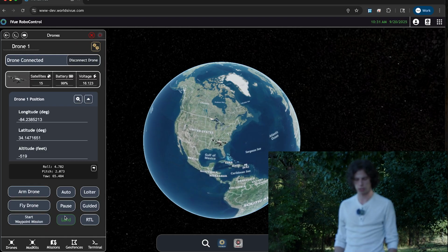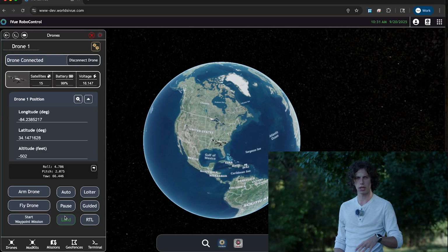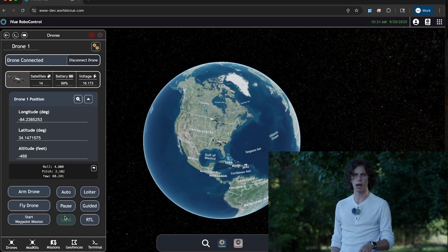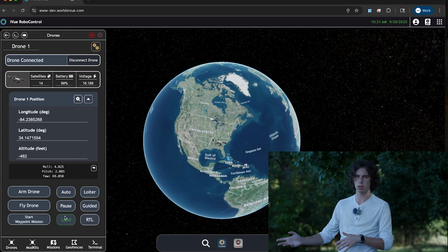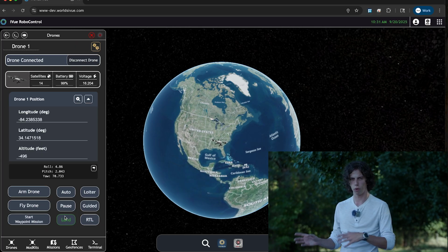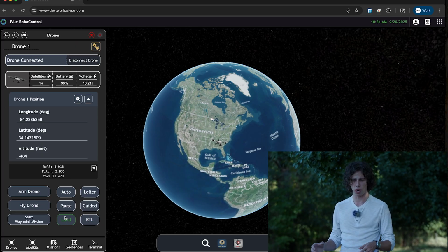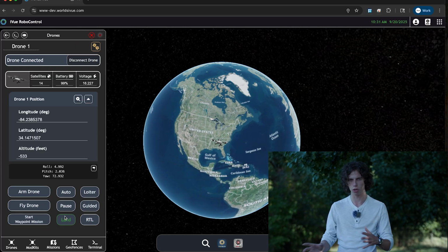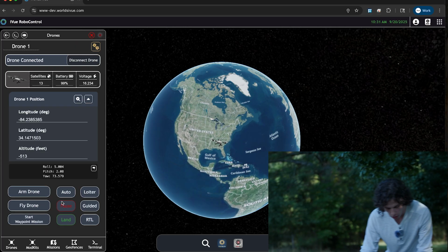So the last thing I think we need to test out here is doing a test flight in QGroundControl. We could also use Mission Planner, but just QGroundControl is a little bit more intuitive. And so if we're not running into this problem in QGroundControl, it's definitely a problem with our software sending commands erroneously.